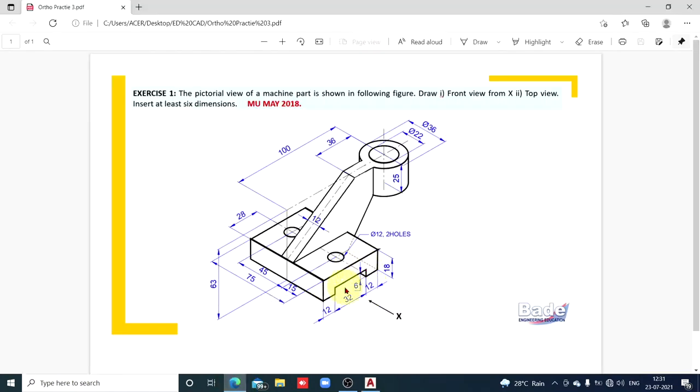Now let's draw this slot. Its opening is visible from the front, and on that front surface of the lower plate, that opening is placed symmetrically. From the left end it's 12, from the right end it's 12, and the middle portion, that is the opening, is 32 millimeter long and height is 6 millimeters.